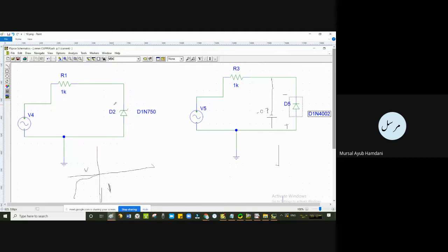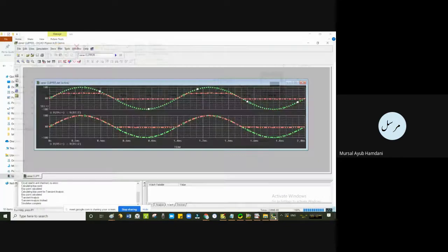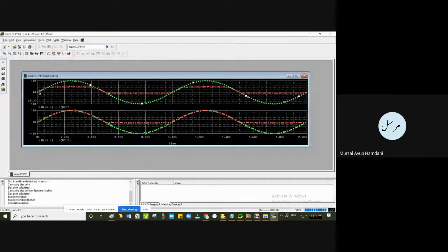In the reverse bias condition, when the positive half cycle is there, we'll have this condition. Positive, negative. After Vz, we'll have this particular value coming about. You can clearly see from this figure that it follows the input till Vz, because till then it will be open circuit.